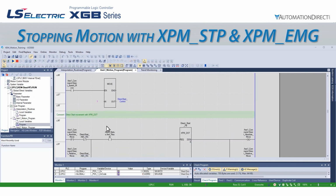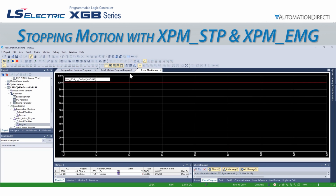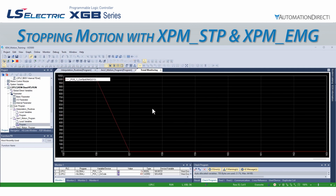We can do the same thing for our emergency stop command. Let's go to line 90 of the code, trigger our direct start again, go back to our monitor and verify it is moving. Again, we see the speed is at a constant 1,000. We can now go to line 35 of the code and trigger our emergency stop. If we go back to trend monitoring, we see that the axis has stopped.